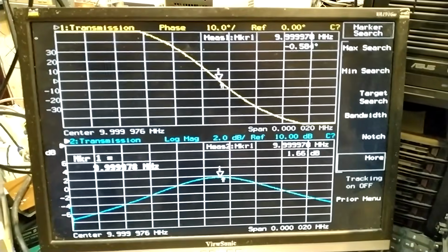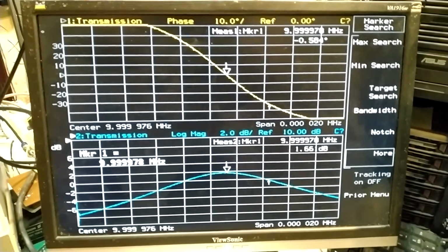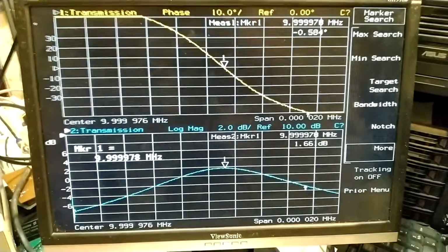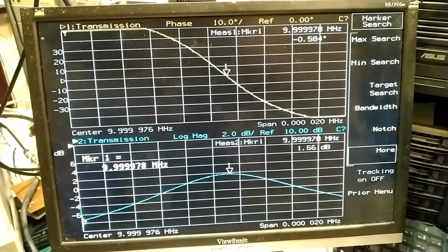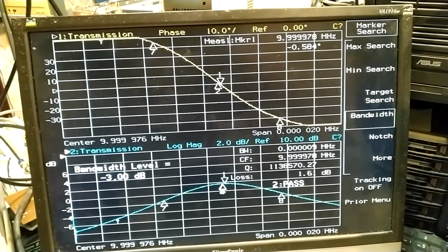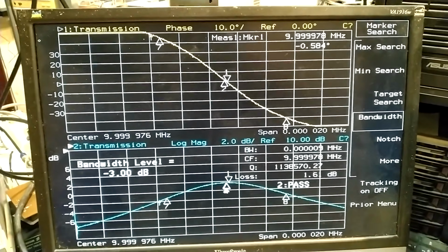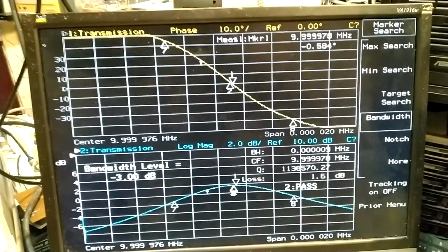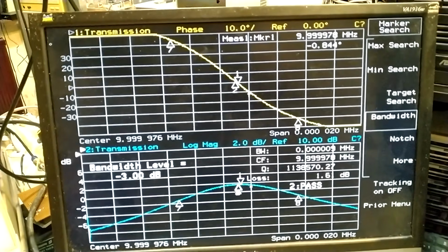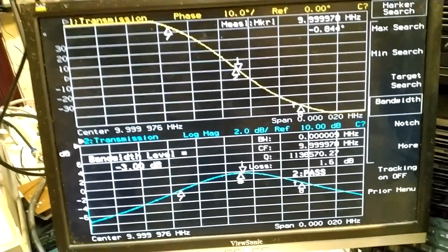I have reconfigured the filter. Now I'm sending a current into it through a transformer. Q is the same, phase is 0 at the correct place, the frequency is about 1.5 Hz higher.